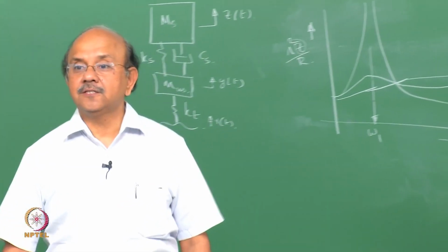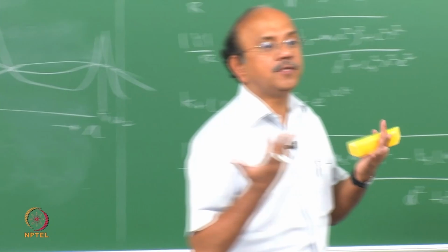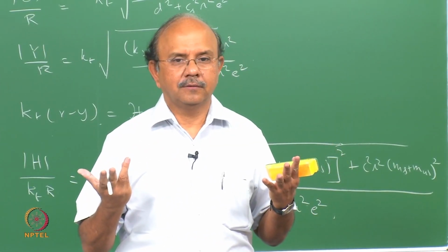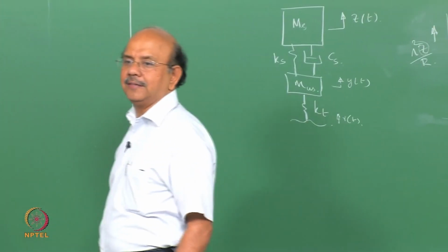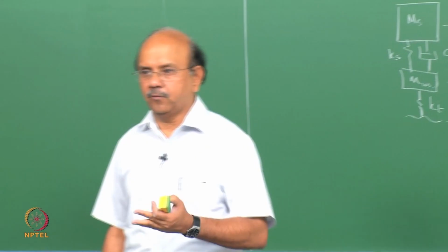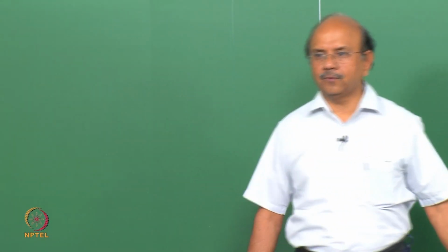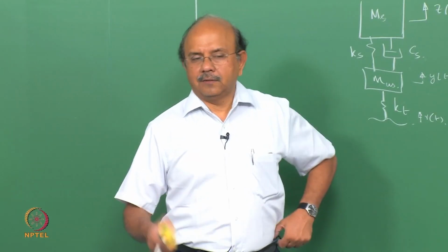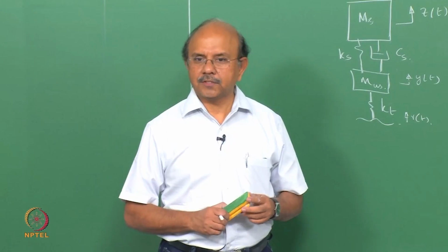Under these conditions, damping optimization becomes difficult. How do I dampen out? Number one, that is why you have techniques where the damping varies with the frequency of excitation, and that's in the realm of controls. But every car does not have it. A lot of things are still in what you call the experimental stage.